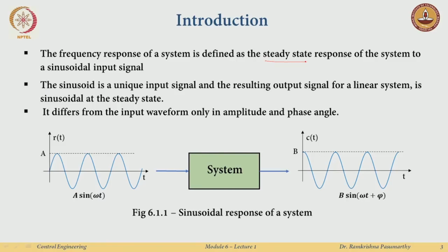The reason we study sinusoidal signals is that if I pass a sinusoidal signal through an LTI system, the output is also sinusoidal. Of course, what will change is its magnitude, and there will also be a phase shift depending on what is sitting inside the system. We will exactly characterize how the magnitude B will change based on what is sitting inside, and similarly how the phase phi will change.